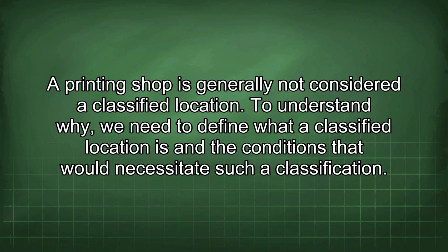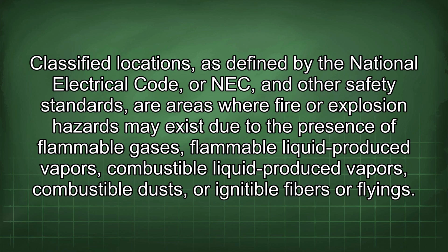A printing shop is generally not considered a classified location. To understand why, we need to define what a classified location is and the conditions that would necessitate such a classification. Classified locations, as defined by the National Electrical Code, or NEC, and other safety standards, are areas where fire or explosion hazards may exist due to the presence of flammable gases, flammable liquid-produced vapors, combustible liquid-produced vapors, combustible dust, or ignitable fibers or flyings.